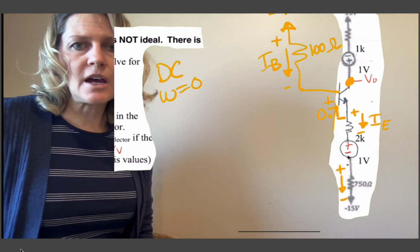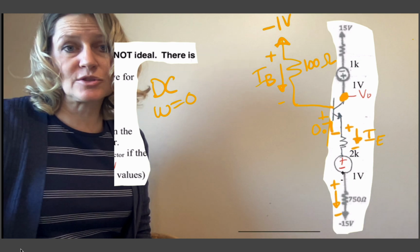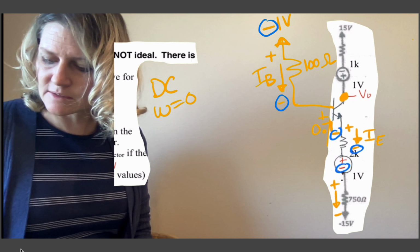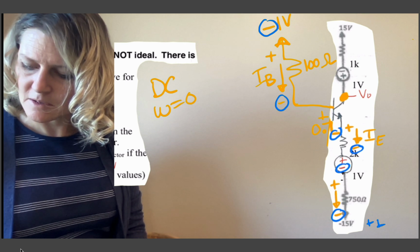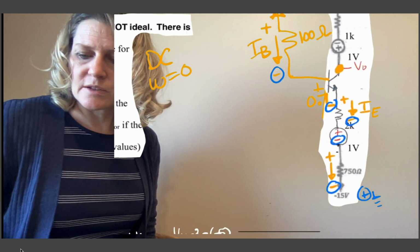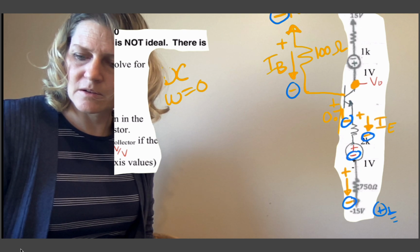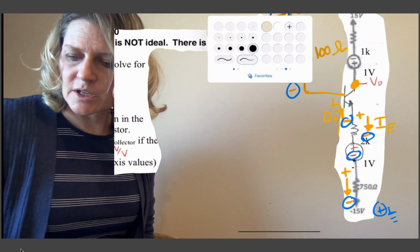So as I take, again, when we solve for the DC, we're going to take a loop from the base to emitter. So this will be a minus, minus, minus, and then this will be a plus 15 volts. And so my loop here, I'm going to write that out.